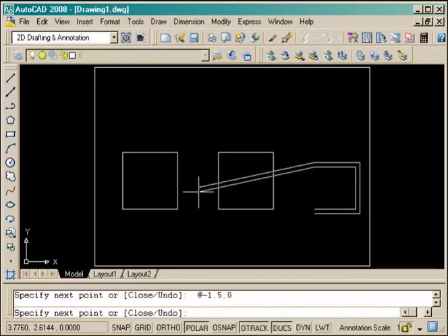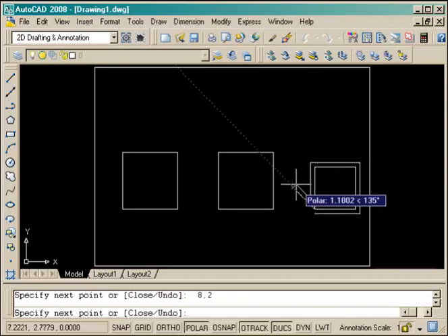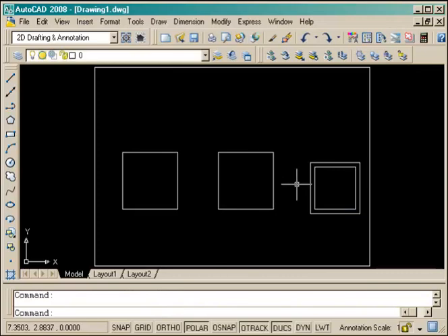If I was to go back to my original point, you would see that it doesn't quite close in the bottom left corner, meaning the outside lines won't close. So what I want to do instead is use the close command so that all lines get closed and it ends up looking nice and clean. But once again, that's not something you might be using a lot, though there are certain areas of drafting that will use it.